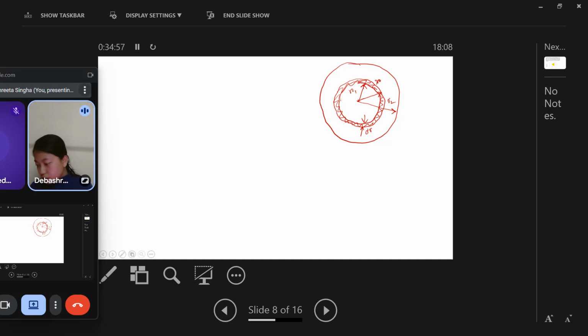We can directly calculate q. Q is given by minus kA dT/dr. What is changing for radial systems like cylindrical and spherical systems is always the area. These are variable area systems. What is the area of a sphere? It is 4 pi r squared.